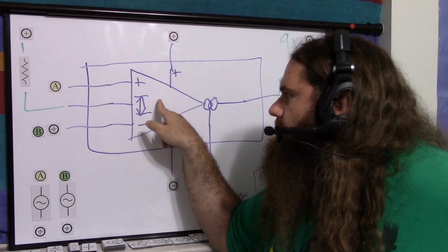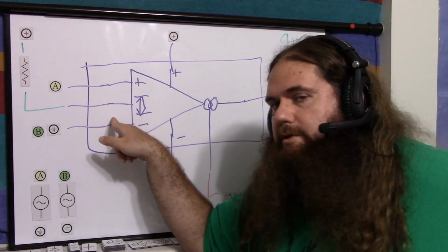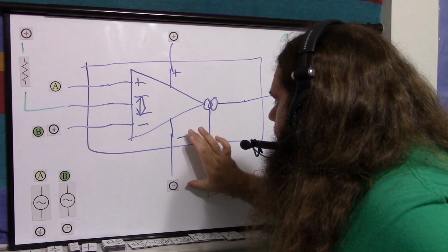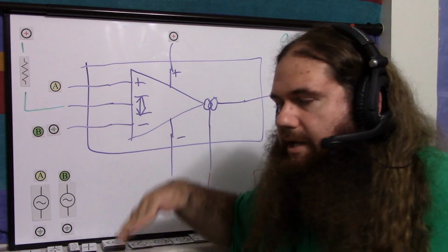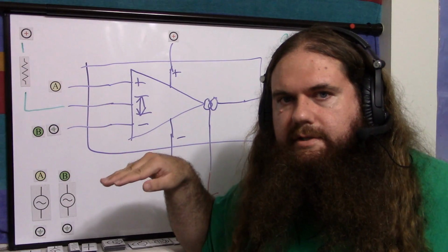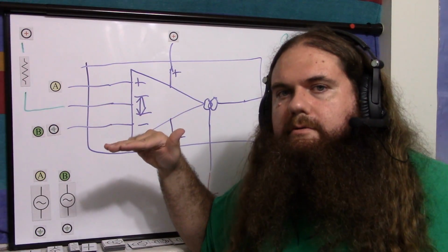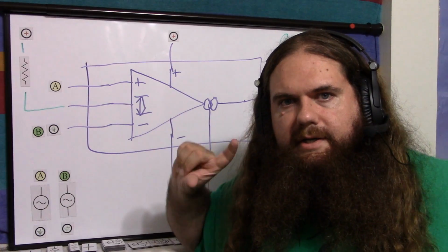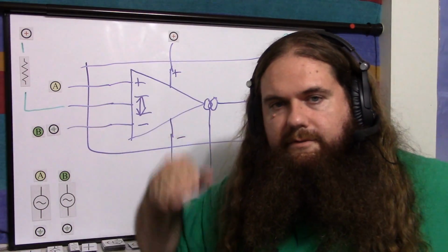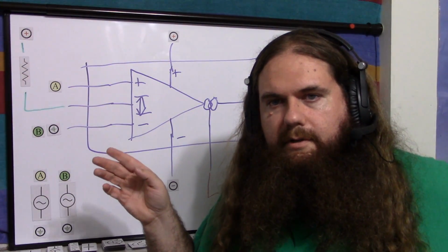It says that the voltage at this pin is going to be 1 diode drop above circuit ground. Now, there is no circuit ground input here. This chip doesn't know what circuit ground is. So I'm assuming that it's just between positive and negative, it's halfway. Because you're usually going to have like 9 volts and minus 9 volts, so it'll divide evenly into 0. I imagine that if you had 9 volts and 5 volts, then this wouldn't be 0. But you're probably going to have plus and minus the same value. But that's what the datasheet says. The datasheet says 0 volts, but they're assuming that you're going to have positive and negative the same number. This chip has absolutely no way to know what circuit ground is.